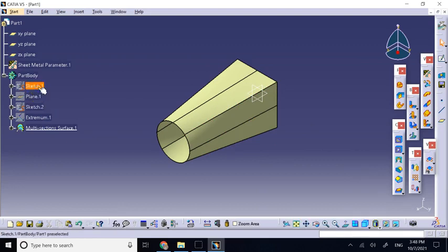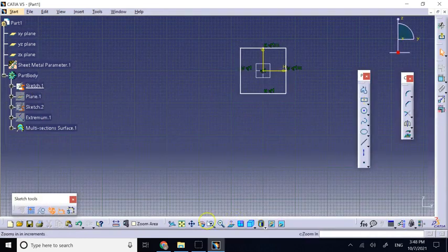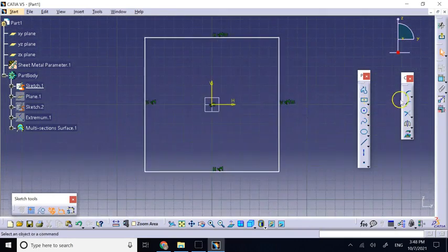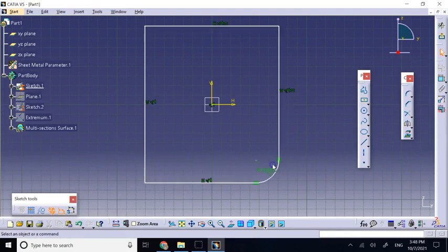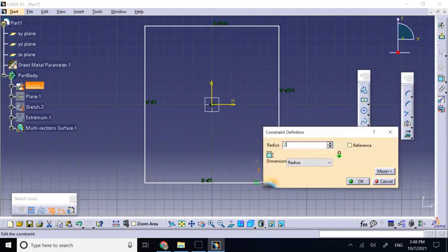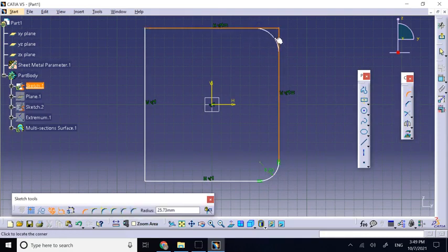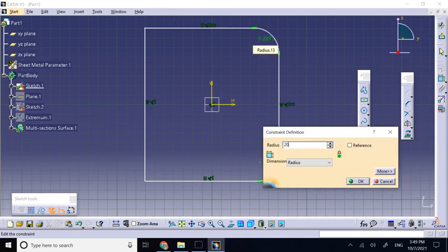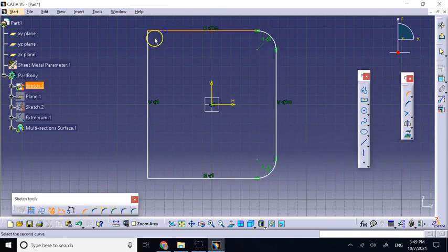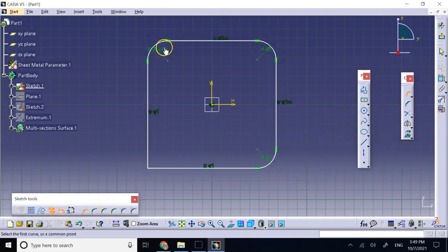So if it does, you need to go back and fix that square that you made, get rid of the sharp corners, right? So use the fillet command here, right? Let's say I use 20 radius on all of the corners, and then do it.